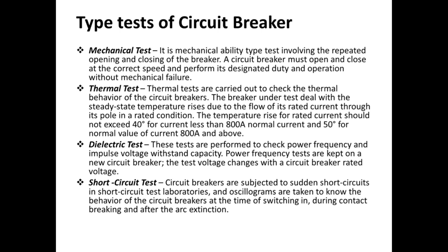So next is the dielectric test. These tests are performed to check power frequency and impulse voltage withstand. Power frequency tests are kept on a new circuit breaker. The test voltage changes with the circuit breaker rated voltage.